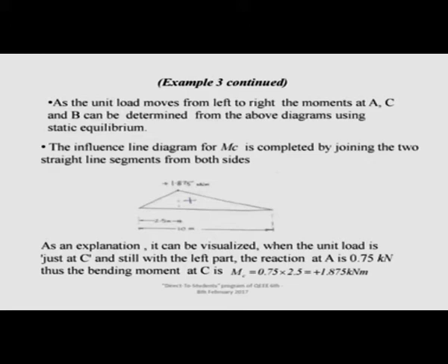What we mean to say is that we are sitting here on the structure, and the unit load is moving over us, and I am trying to feel how the bending moment where I am sitting is actually changing with the location. You can check the maximum will be here because the beam will bend most, and also it will be 0 where it is on the supports because the load will be directly transferred to the support.